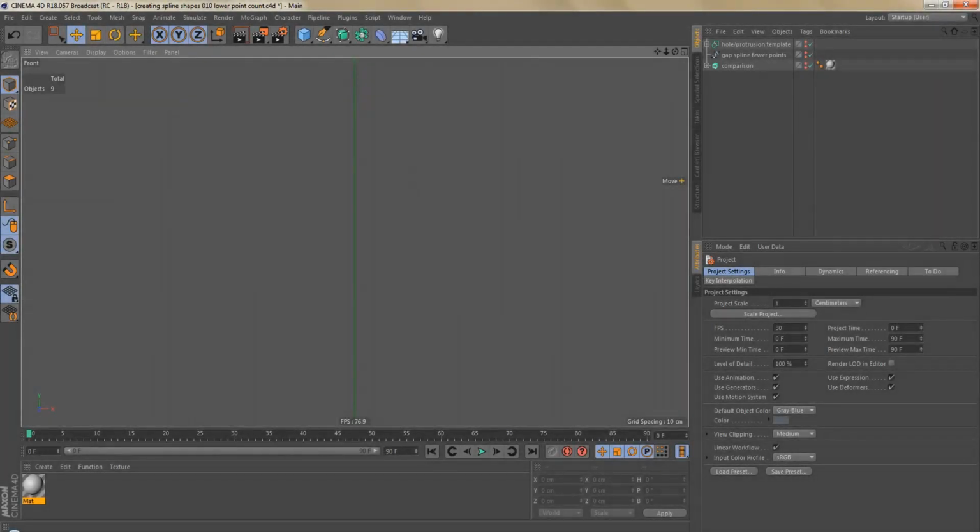In the previous videos I showed you what I think was the easiest and most accurate way to create the jigsaw puzzle. Easy because we didn't have to do a lot of manual drawing or tracing or tweaking, and accurate because we were able to use parametric splines as a basis to create certain sections on our spline shape. However, I didn't want to conclude this tutorial without mentioning that by keeping things very easy, I also broke one of the basic rules. And that rule is that you should use as few points as possible to define your spline shape.